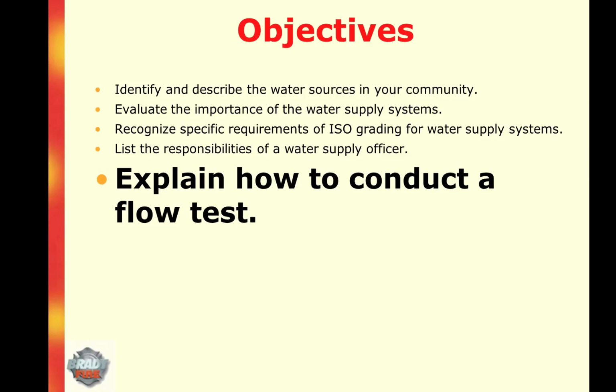In gridded systems, water will always flow from larger water mains to smaller water mains, and when choosing the flow and test hydrant, the inspector should determine the flow direction to establish the test fire hydrant closest to the construction site. Residual test hydrants should be in the direction of the water flow, and in some cases only one fire hydrant may be available and will have to serve as both the flow and residual test hydrant.